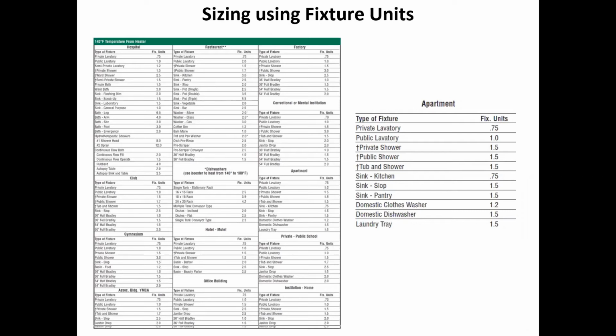So anyhow, if I'm sizing this apartment, I'm going to use these numbers here. I have documents that were provided by our company, and I just like to use the tools that were given to me. So I use this unless there was a more updated fixture unit sheet, then maybe I would consider that, but this is what we have at this time.